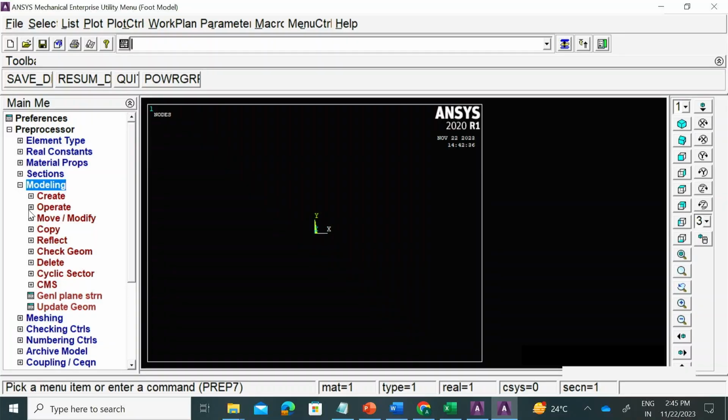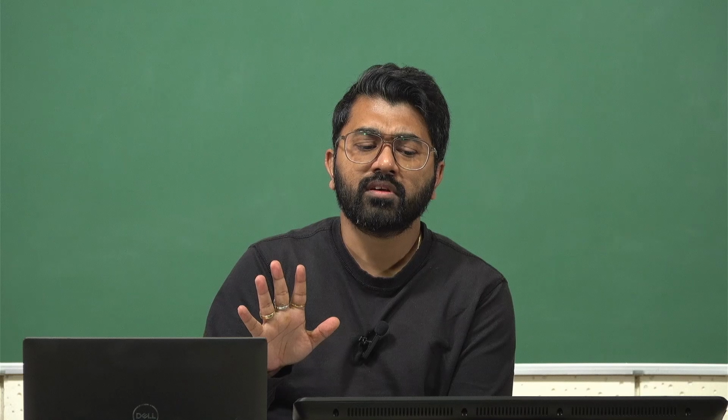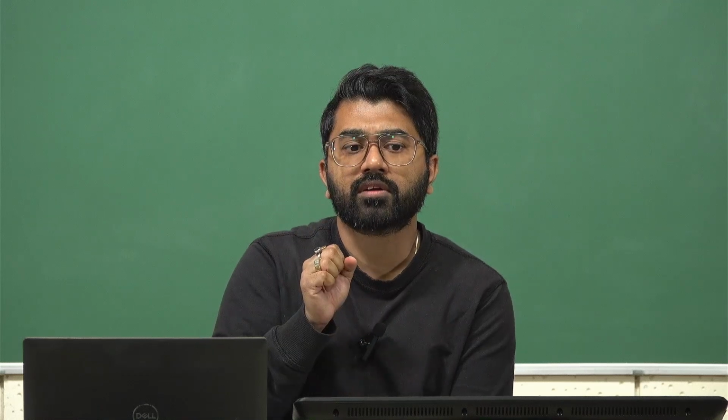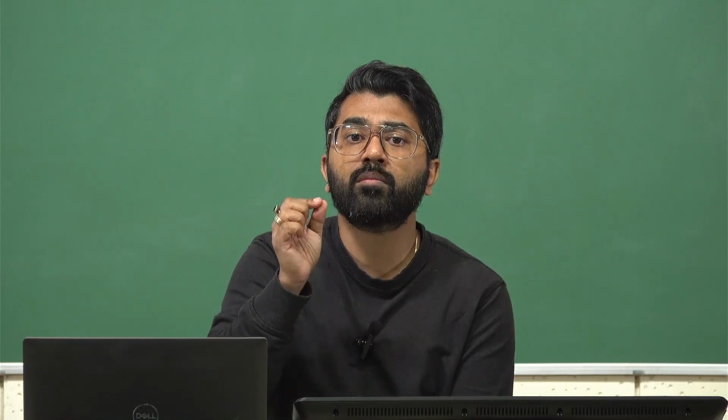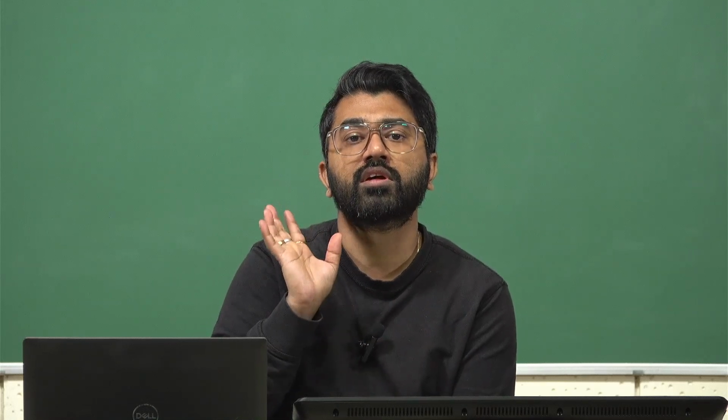So the next thing which we want to look at is not all bodies overlap, right? What if they are just touching each other? Then what is the criteria there, right? So as we know that in ANSYS, the computer does not understand any interaction unless there is an operation which is creating that interaction. So when we have just two bodies in air, even though they may be touching or may have an overlap, the computer will not understand that unless you apply the overlap operation or create a contact condition for the touching bodies, right? So that should be very, very clear.